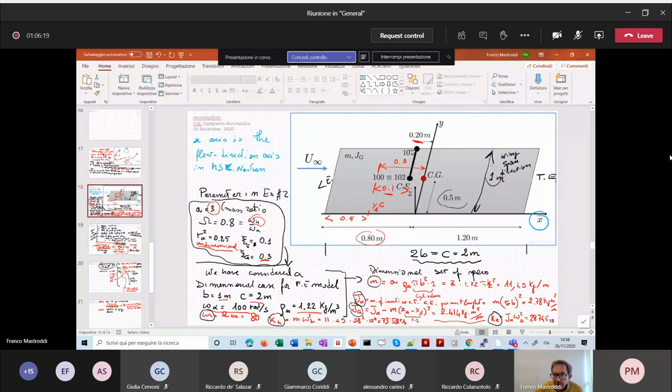Here we are considering this double grid element connected by a rigid bar, because we need these two grids for modeling our wing, because we have to define an interpolation strategy between the structural and the aerodynamic degree of freedom. So the double definition of the node 101 and 100 is artificial.